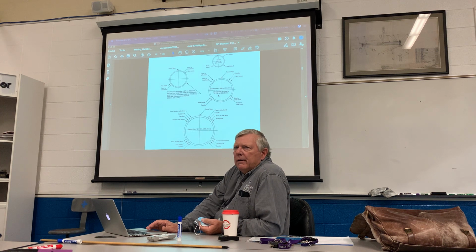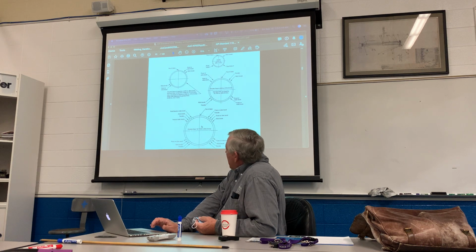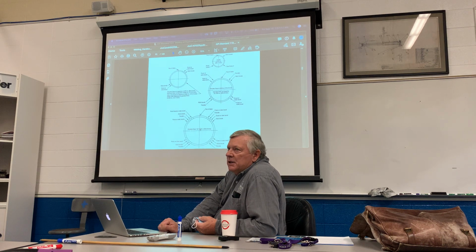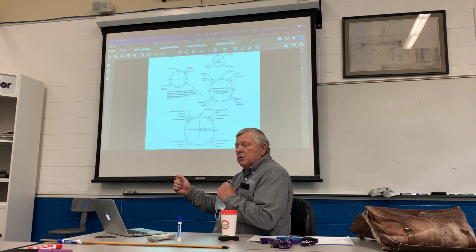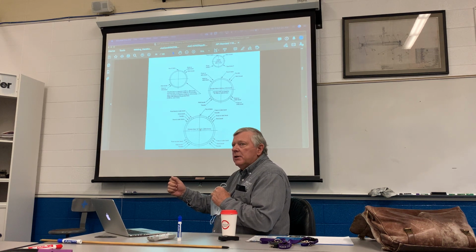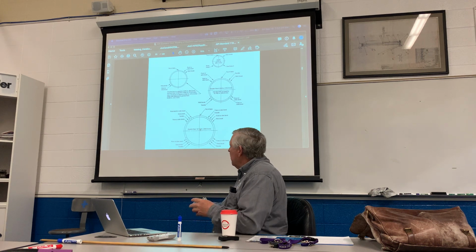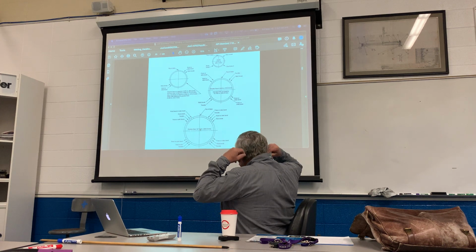Well, what do you do then? Technically speaking, it lapses you over into this size, doesn't it? Technically speaking. But if your MTR, the document that tells you about the chemical composition and the heat number of that pipe, says it's 12.750, then you're dealing with 12-inch pipe. You just leave it at that. But I've run into this before a couple times.